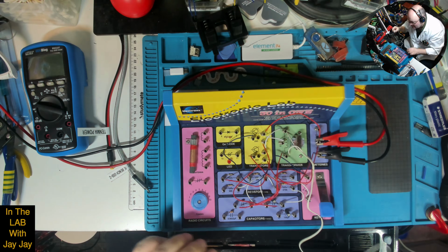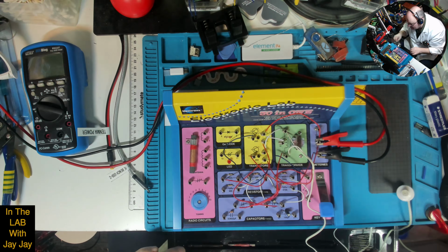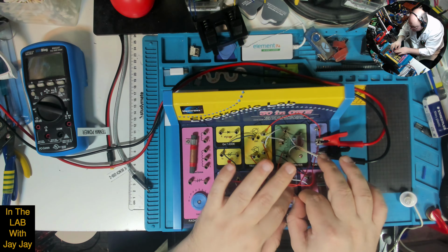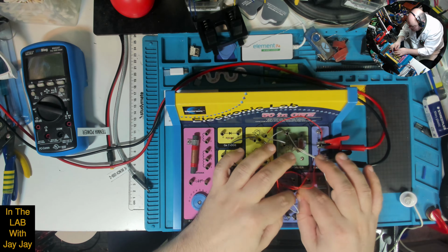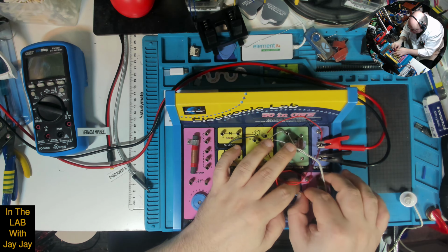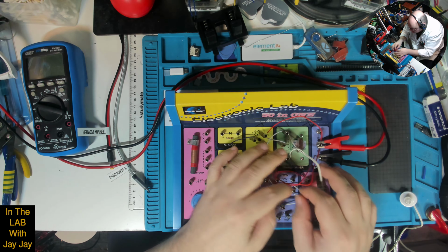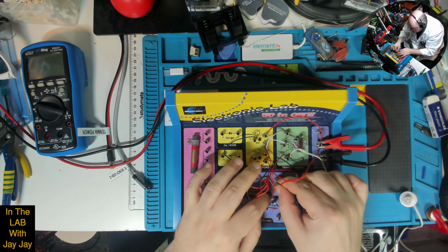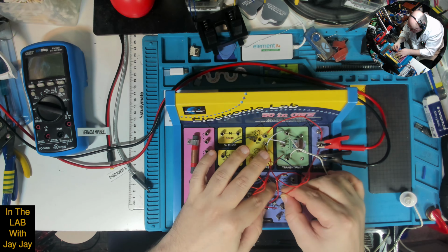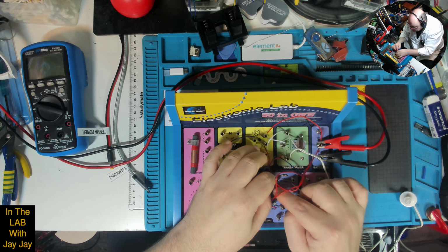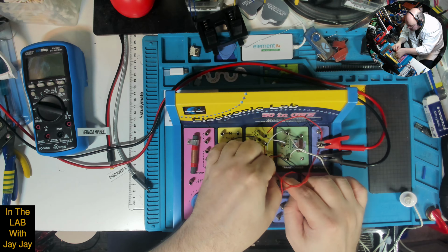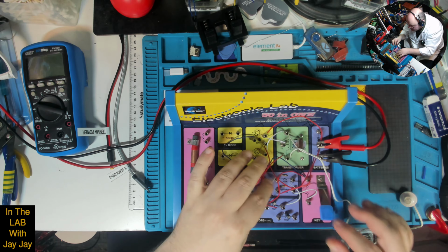Well, that's all well and good, but let's try switching it around so that the 470k resistor is at the top and the 100k resistor is across the capacitor. That might give us a shorter decharge cycle, and the tone might oscillate more quickly. I'm not sure how the top one will affect things. Let's try that and see how we go.